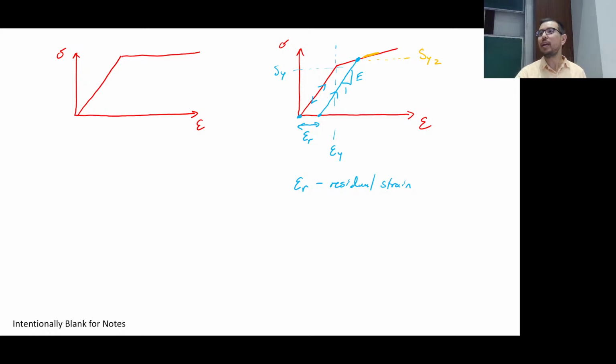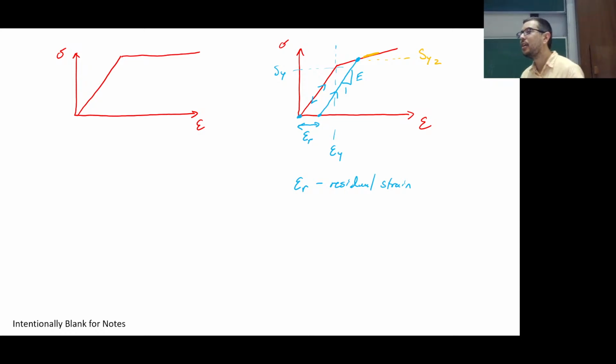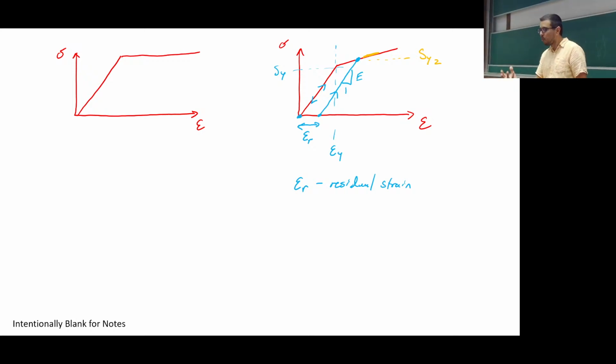Does strength only happen in the region where the necking occurs, or throughout the whole bar? Yeah, that's a good question. You can have different amounts of local plastic strain, so it'd be variable. Where you have the most plastic deformation is going to have the most strain hardening.